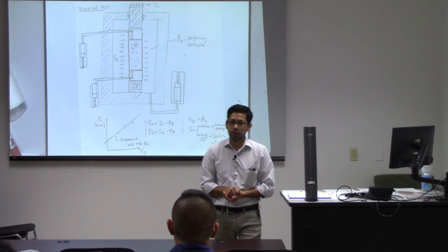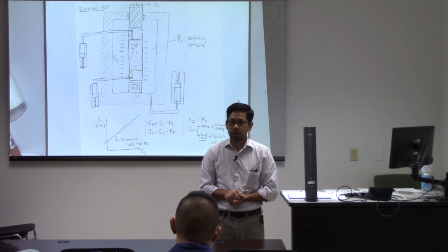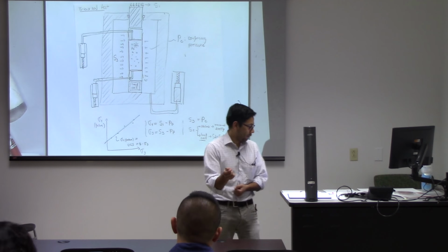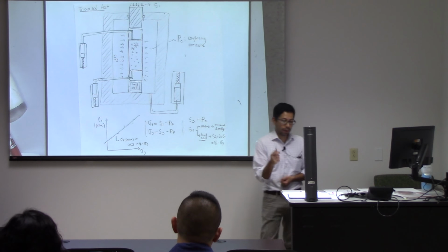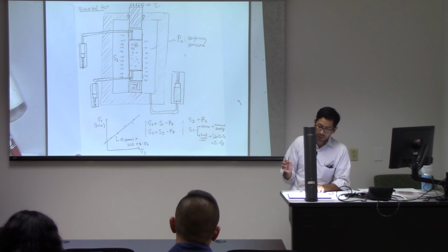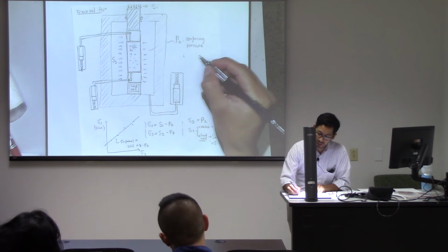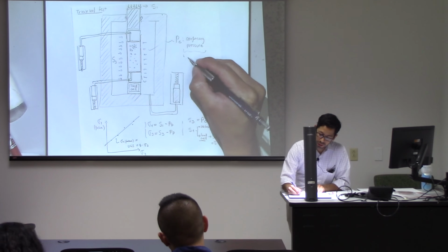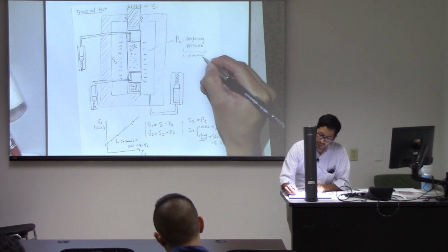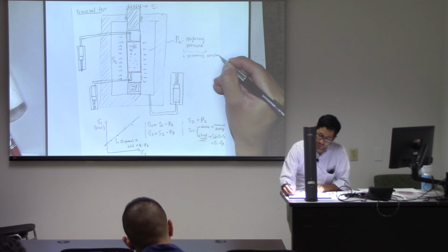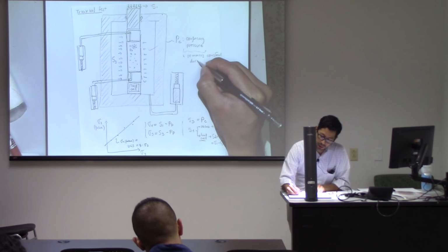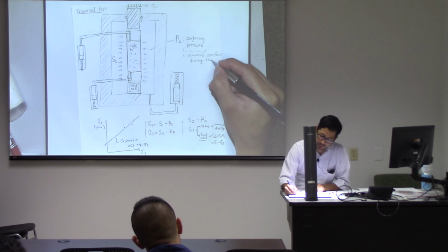Yes, A1. So wouldn't the sigma 3 just remain constant just because it's pore pressure? Would we be changing that? Very well. I forgot about that concept. In all these kind of tests, in a triaxial test, confining pressure remains constant during the test.